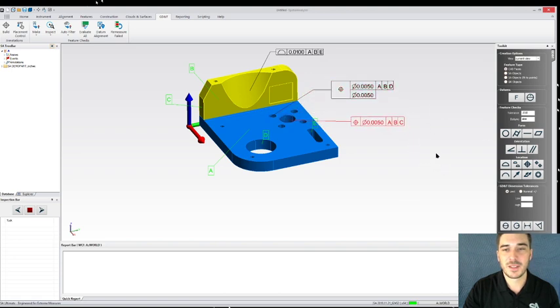There we go. And we need to make one modification to our composite true position. You can see that we've got a tolerance of 5 thou to A, B, and D. And then what we need to do is add a datum to our lower frame there that lets us know what reference we need. And we'll probably change the tolerance on that as well. So I can get to that just by right-clicking and selecting Properties. And then you'll see my Annotations dialog pops up.